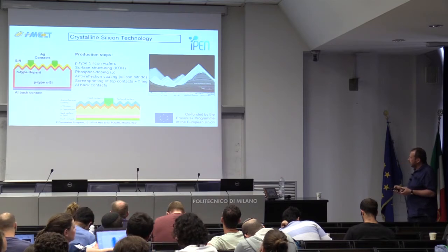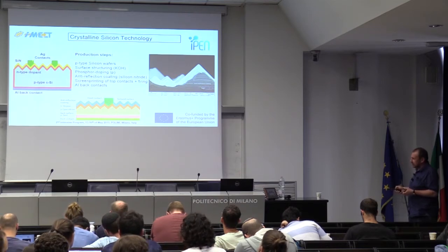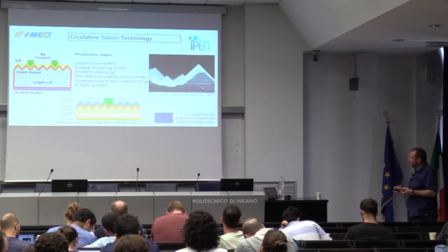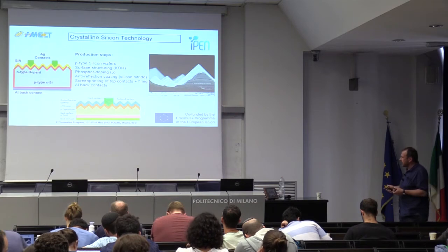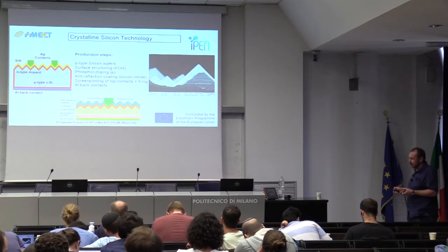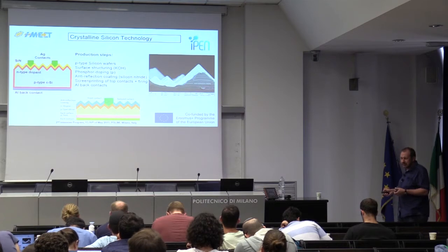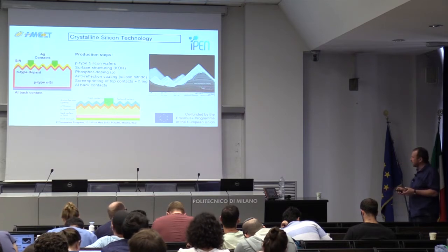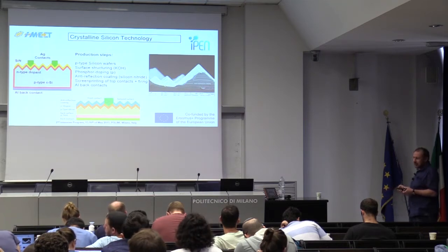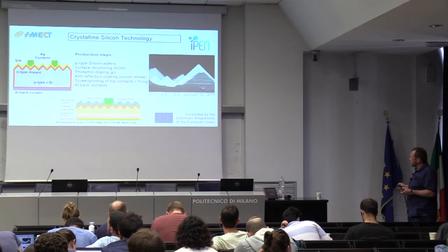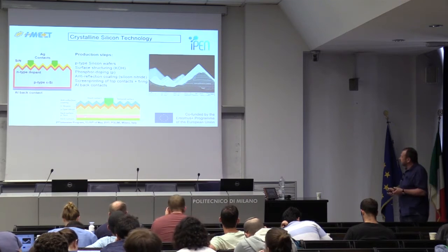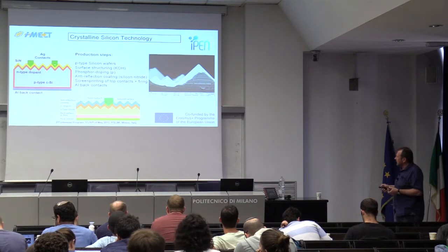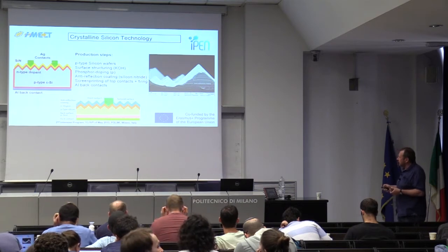After that, an anti-reflection coating is put on the surface. This is silicon nitride, hydrogenated silicon nitride with a thickness of maybe 70, 80 nanometers. It's a quarter wavelength. And on an electron microscope, it looks like this white layer here is the anti-reflection coating. Here once more the structure, and at the end, top electrodes are screen printed.